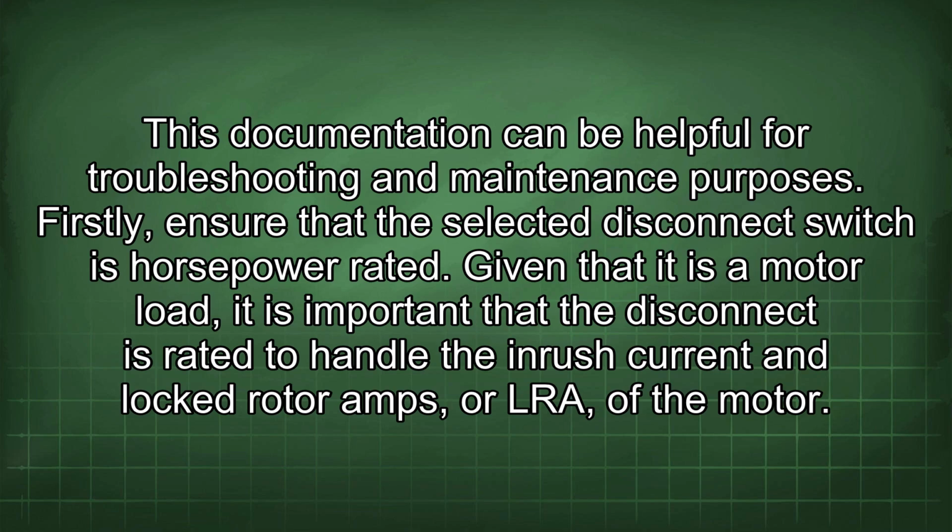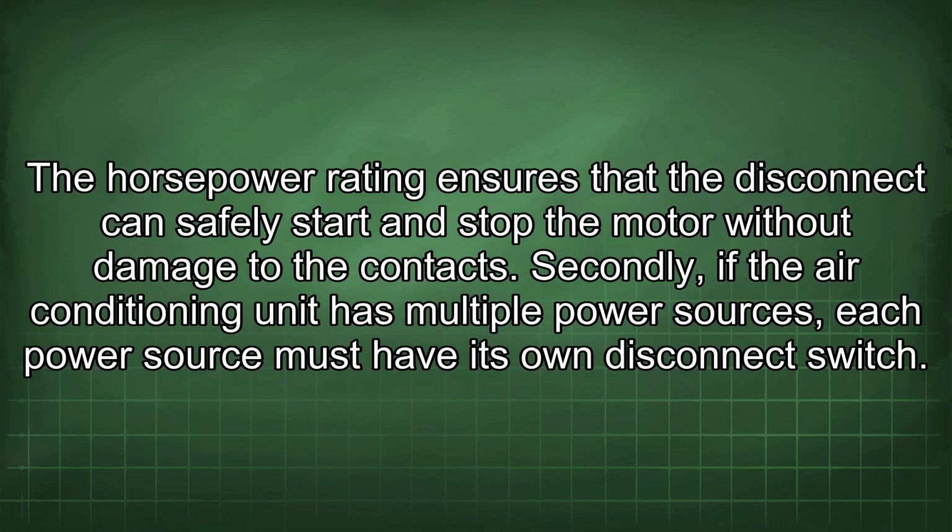Firstly, ensure that the selected disconnect switch is horsepower rated. Given that it is a motor load, it is important that the disconnect is rated to handle the inrush current and locked rotor amps, or LRA, of the motor. The horsepower rating ensures that the disconnect can safely start and stop the motor without damage to the contacts.